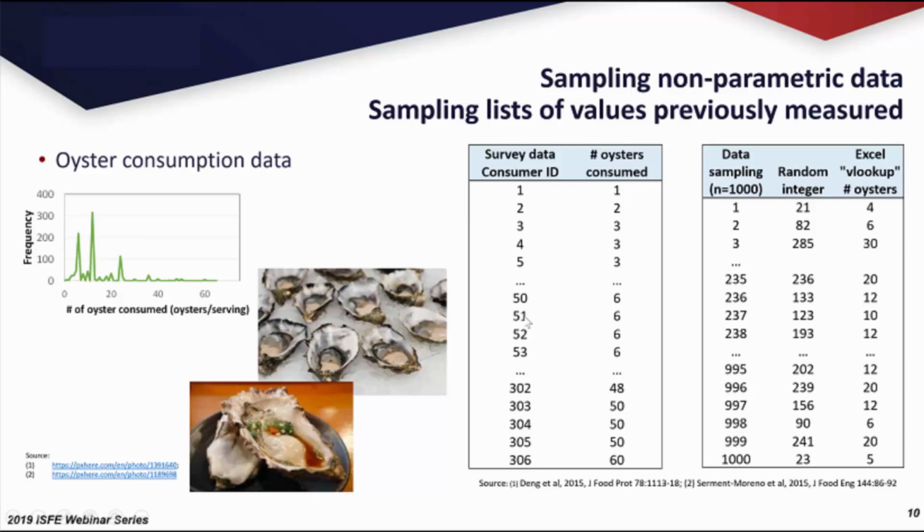We're not talking about mixing a fresh piece of meat with some dry berries. I mean, that will not happen. Usually the product will have fairly similar initial but different water activity. So this slope here will be a fairly good description of the isotherm. And this is how much of each ingredient, described as the mass of solid of each ingredient.